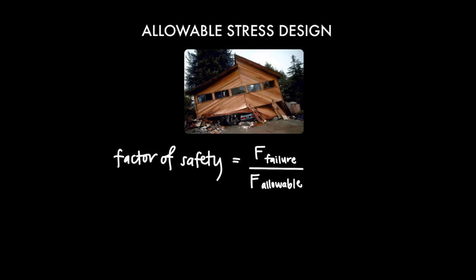Our last key concept involves allowable stress design. This basically boils down to the idea that although a structure can support a large load, we probably shouldn't push it to its limits. Otherwise, we may end up with this. We use a value called the factor of safety to determine the amount of force a structure can handle. The factor of safety for specific materials can be found in engineering handbooks and design codes.